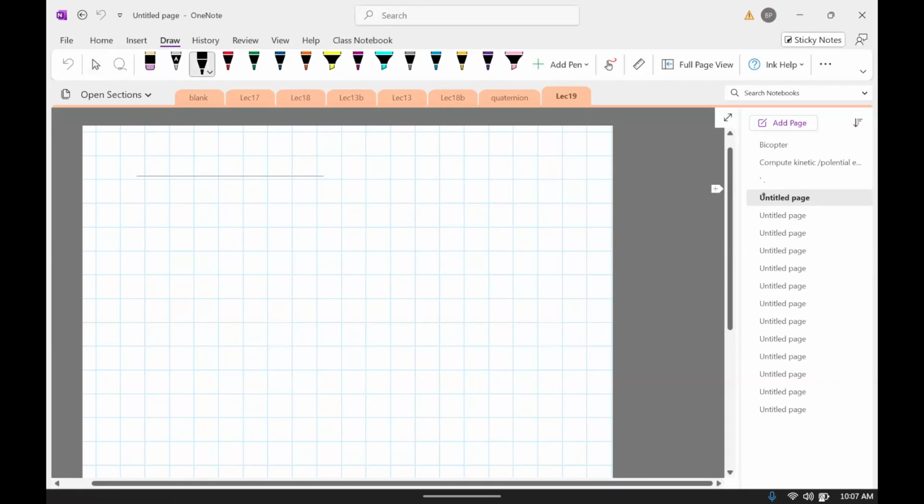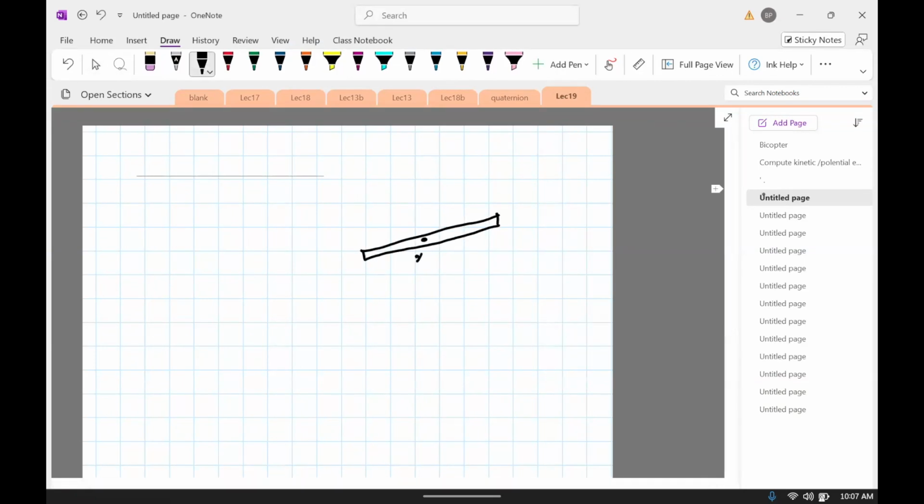So I'll just redraw this figure. X, Y, and then as always we do, we attach a frame which is not going to move. Well, actually, this is not right. This frame is stuck to the floor on the ground somewhere. So let's draw it somewhere like this. And then the frame which is actually going to be attached to the bicopter and move is x1, y1, and this is O1. So what the transformation H10 gives you is essentially, if you remember, it's the rotation matrix. So write it down. This position of point 1, this point, with respect to frame 0, 0, and 1.